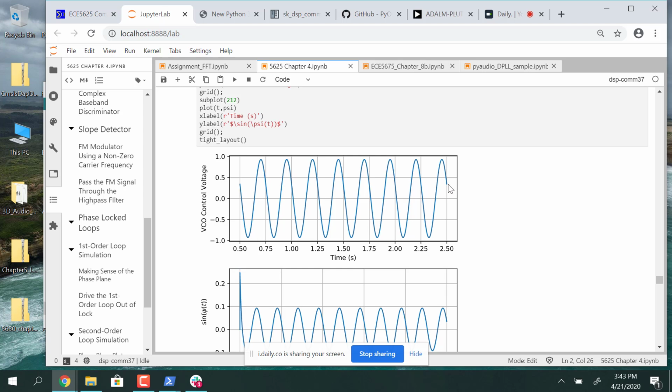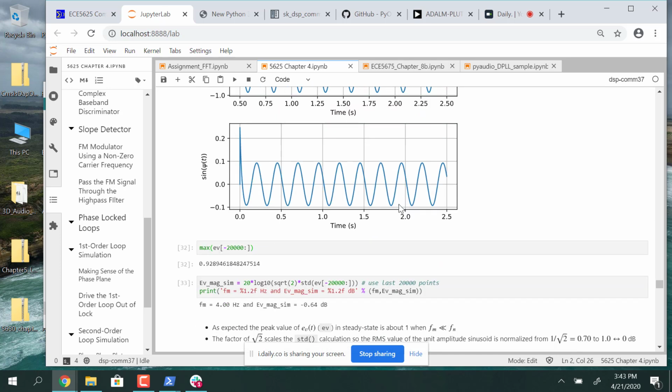If you were in the lab, you might put your AC voltmeter on this signal rather than the oscilloscope, but the oscilloscopes you use in the lab have nice measurement tools on them, right? So you can ask it to give you the peak amplitude, the peak to peak, the RMS, all those other side calculations. We're doing some of that down here in this fashion.